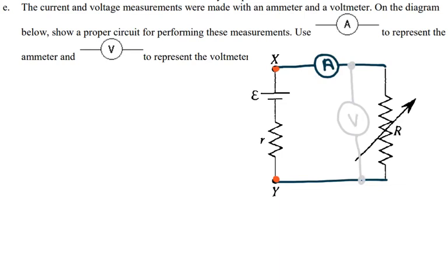And the resistance of the ammeter is going to be equal to 0, because you don't want the current that is flowing. The current is always flowing from the positive to the negative. So you don't want the current to go through the ammeter and drop some voltage. So if the ammeter has some resistance, then the voltage is going to be dropped, and that affects the whole circuit. So we don't want any of the voltage or the potential difference to be dropped on the ammeter.